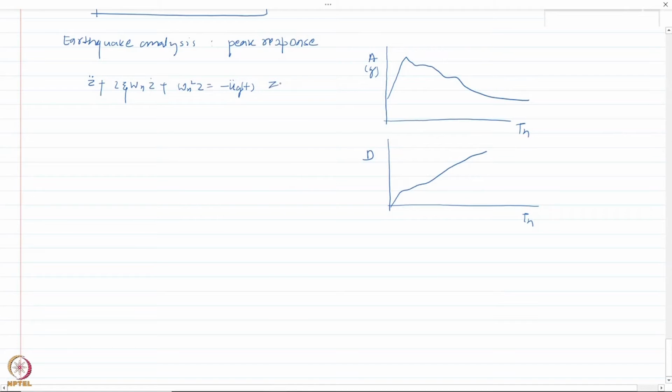But remember, the equation that we have for the generalized system, the left hand side is the same. However, in the right hand side, I have a factor which is gamma equivalent. Okay, now since we are considering a linear system, if I know the peak response of this system, to get the peak response of this system, I just need to multiply this with the factor gamma equivalent. Because my ground motion is now multiplied with this, so the response would again be multiplied with this factor. So the peak response would be multiplied with gamma equivalent.